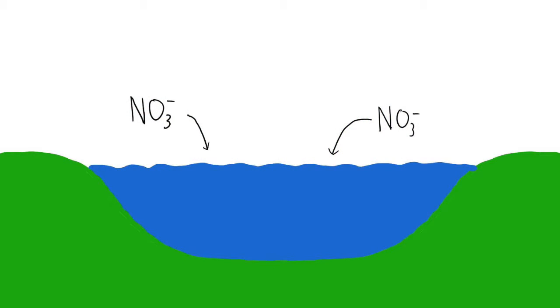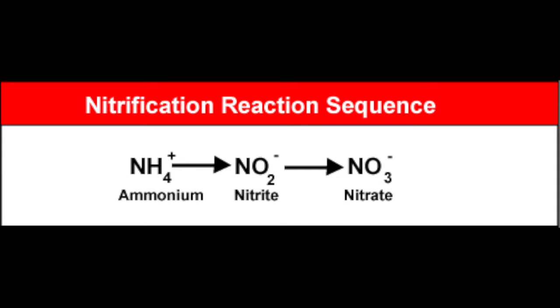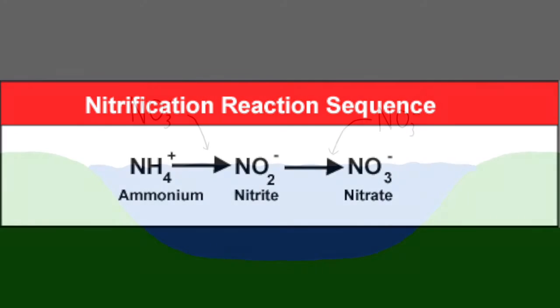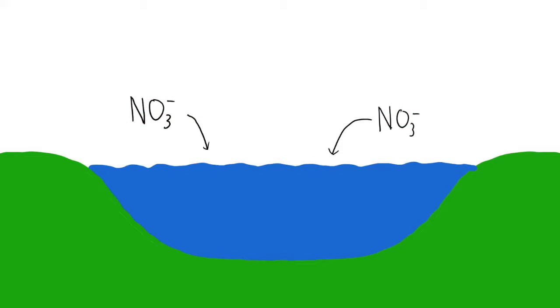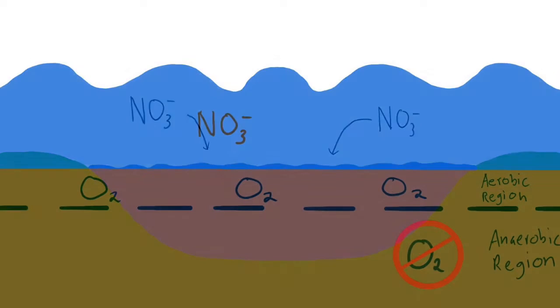Wetlands are effective at treating nitrogen in the form of nitrate, so nitrate can enter directly, or it can enter as ammonium, which can be converted to nitrate through a process called nitrification. Once nitrates have entered the wetland, they move down the water column.